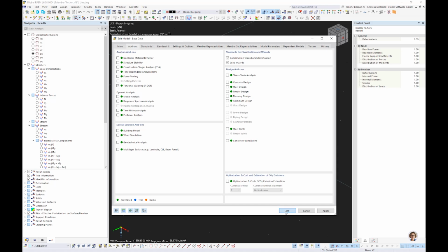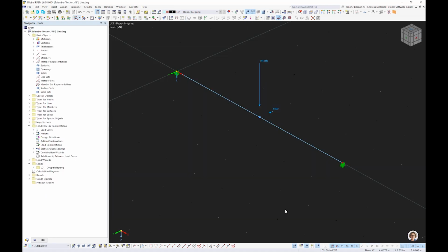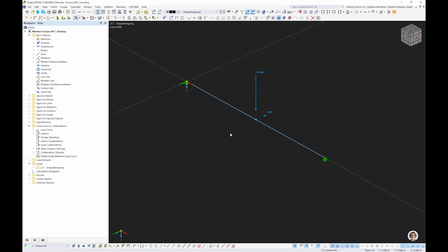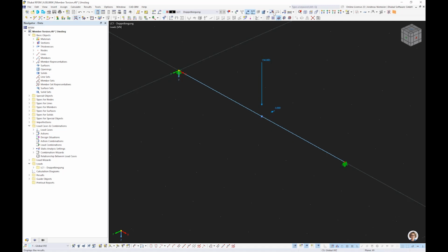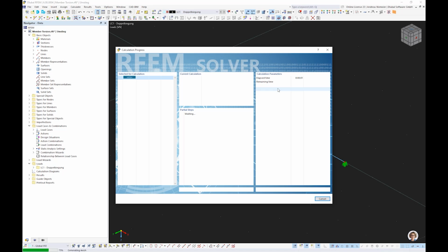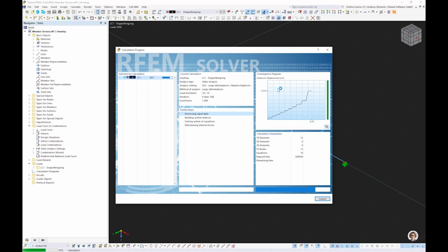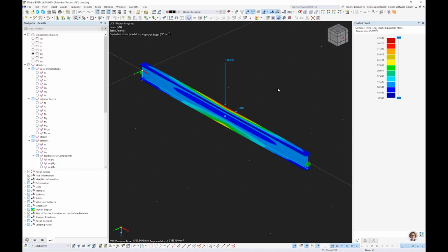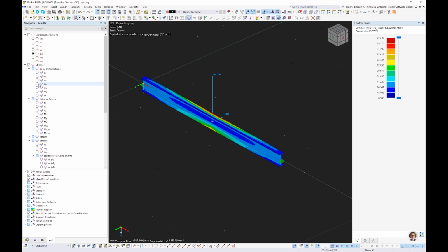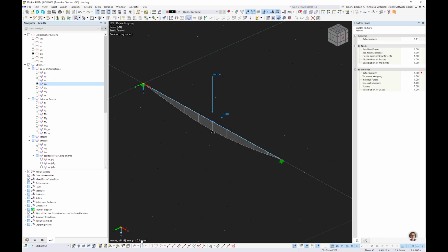You can connect it to first, second, third order as you wish, in branched models or only in one-member models. And if we calculate it now, you get results that fit a little bit more. Now we have an elastic stress of 527. We have a torsion of 81 millirad, so much smaller. Bending moment MY is the same as before, and horizontal is 28, so much smaller.